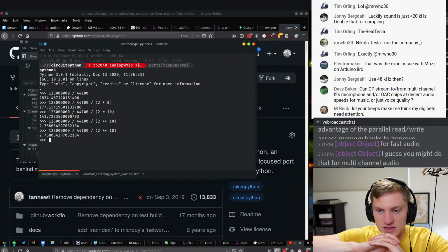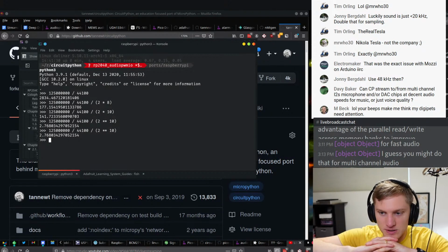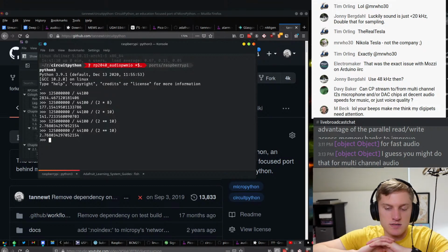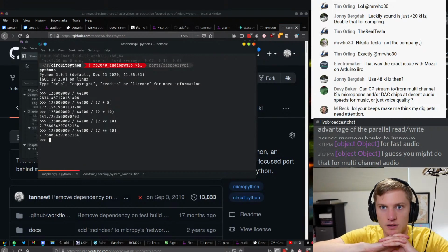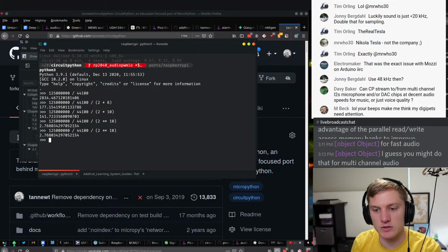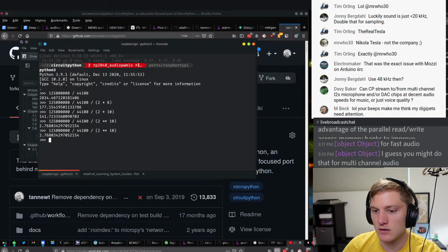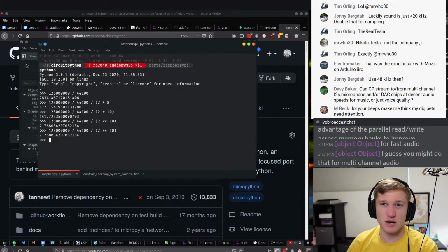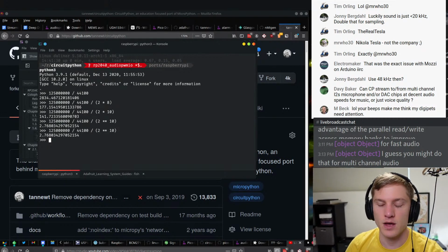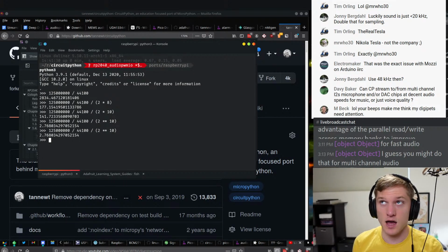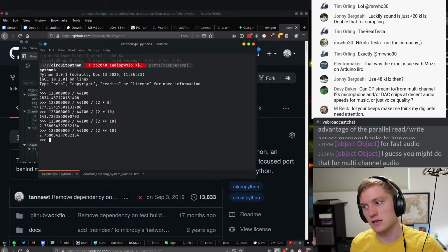Davey says, can CircuitPython stream to or from multi-channel I2S microphones or DAC chips at decent audio speeds for music or just voice quality? We haven't really focused on quality. I think you'll find that just because this chip is pretty powerful, we'll be able to do higher quality stuff than some of our other boards. But it's really just a matter of how much CPU time we have. We can only do I2S out right now. We cannot do I2S in yet.